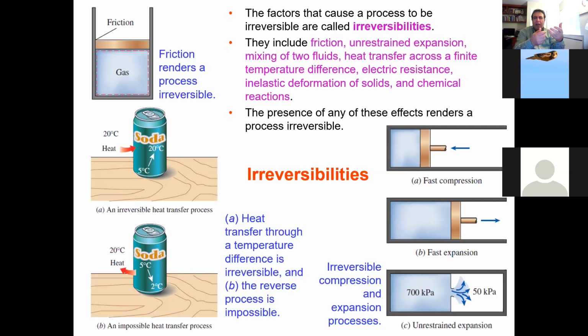I like to do the test on ductile materials because you can see that the material is going to stretch and doesn't snap right away. When you apply the tensile load and then remove the load up to a certain point, which we call the yield point, the material will return to its original position. So that's a reversible process. No harm is done on the material. The material stays the same.